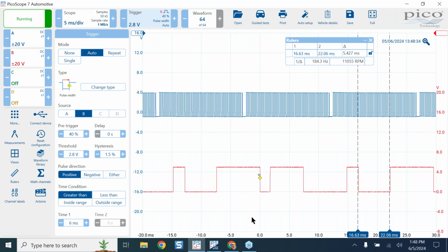I find it especially useful for ignition, when ignition is bouncing around all the time, especially when the engine is running. Triggering on the vertical, triggering on simple edge, the scope doesn't always trigger well. It will bounce around. We call it jitter. So if the scope is jittering a lot, maybe moving to a time-based trigger and not a simple edge is going to help. We've even got an advanced simple edge with hysteresis, and it still doesn't always work really well for ignition. So I like to use the time-based trigger for that.